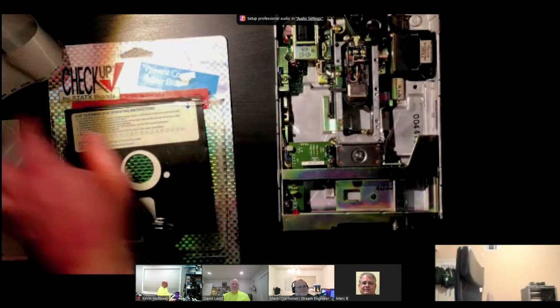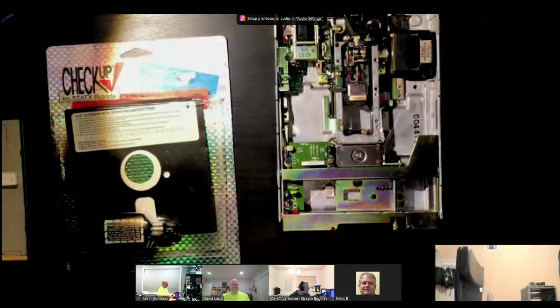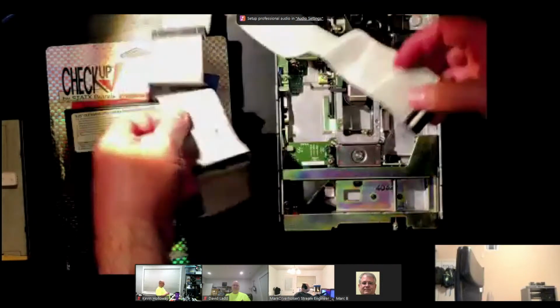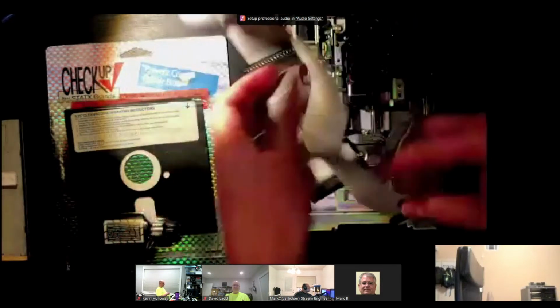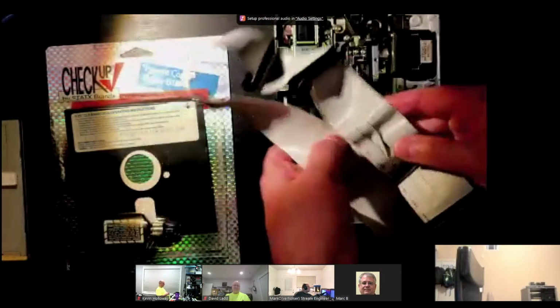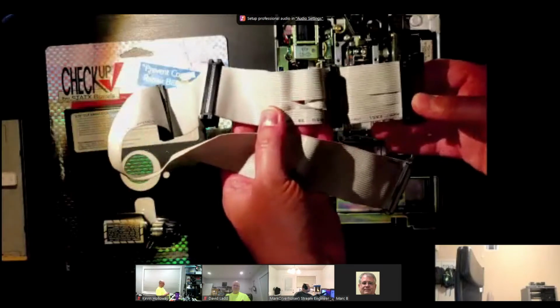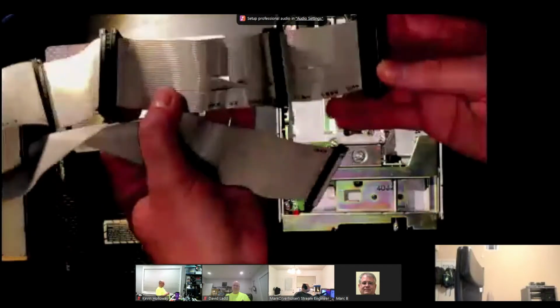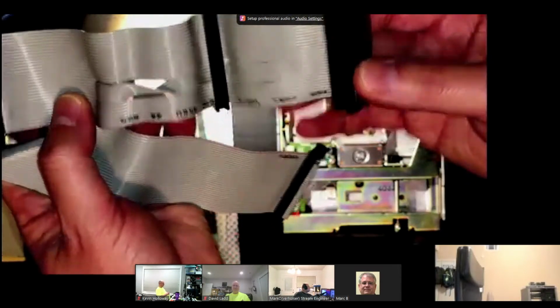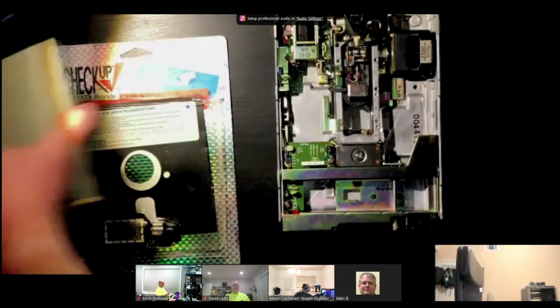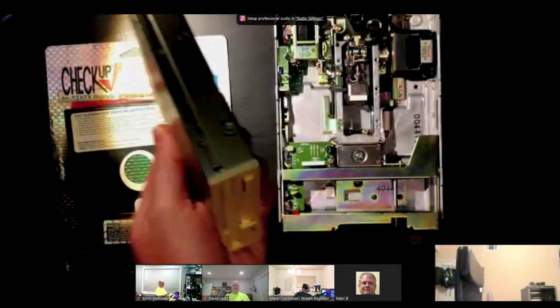Yeah. So let's move along. To properly use the Greaseweazle, you of course need a floppy cable. The way the Greaseweazle is normally set up, it's set up for PC style, not Shugart style. So you notice this cable has the twist in it here, because this is a standard PC floppy cable. And I have one that has both kinds of connectors on it, so I can do 5.25 or 3.5, which I have the drive here.